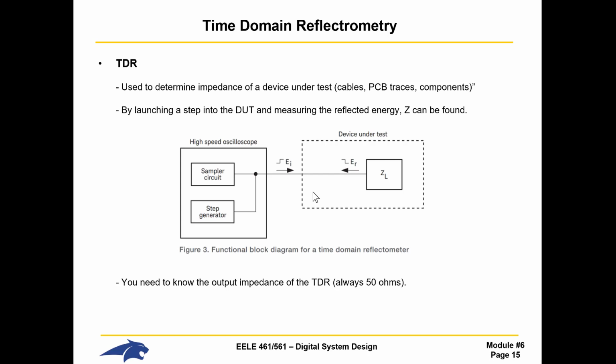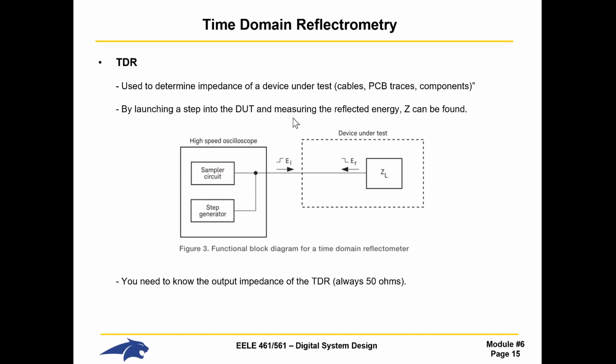We got to a point where we wanted to see this in action. Last time we built an ADS model that had a coupled line, and we wanted to see the impedance of the line that we care about, or an impedance discontinuity, change depending on what the neighbor was doing. It was the first time we were actually trying to measure impedance in ADS, and we looked roughly at the architecture of a circuit that could do this, called a time domain reflectometer. It's such a powerful tool. I want to spend this lecture looking at it, and this is almost everything we talked about last time, so let's just review what it is.